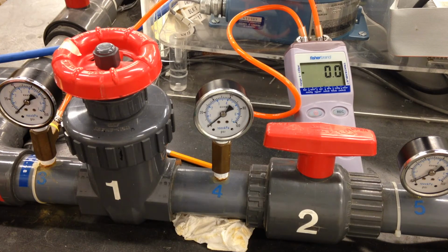Now the inlet diameter of this is 1.48 inches. What I'm going to do is run a quick demo of this. Currently at quarter opening, I'm going to just increase the flow gradually. And as I increase the flow gradually, you can see that the digital manometer likewise increases the head. Now the head the digital manometer records is in inches of water.